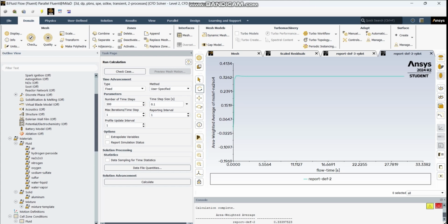I've used a finite-rate chemistry model, possibly combined with turbulence-chemistry interactions. In such a model, mixing directly influences the rate at which reactants meet and react.